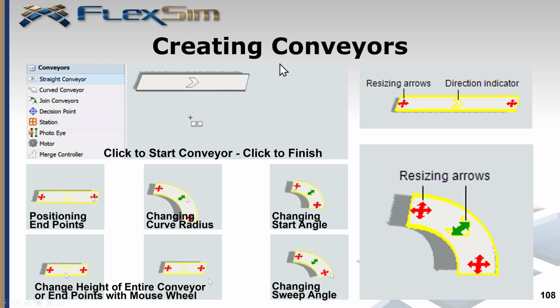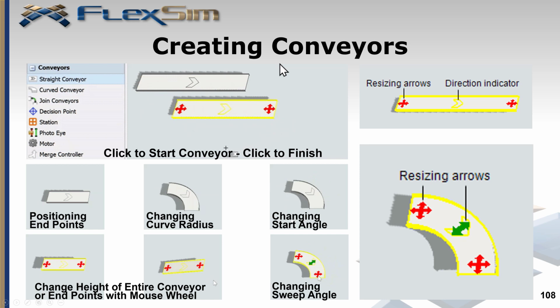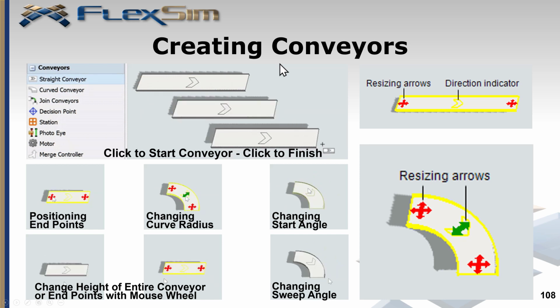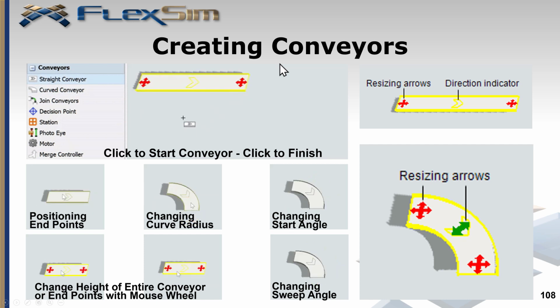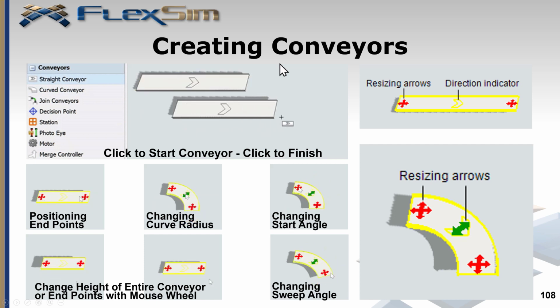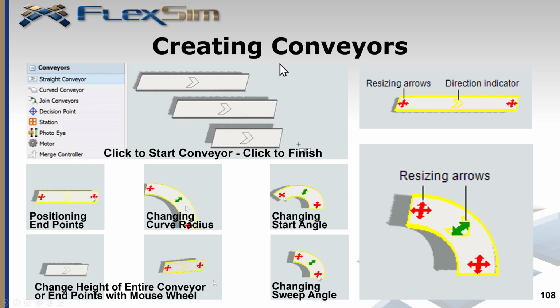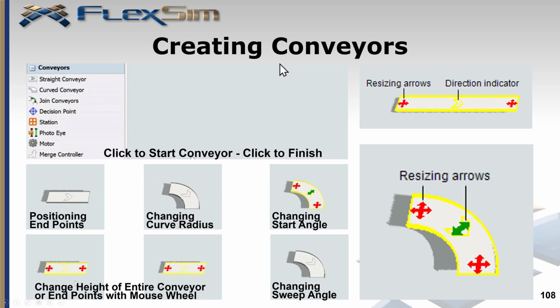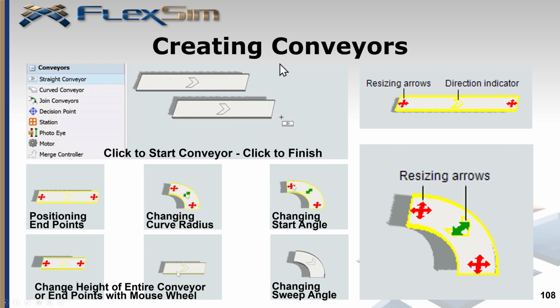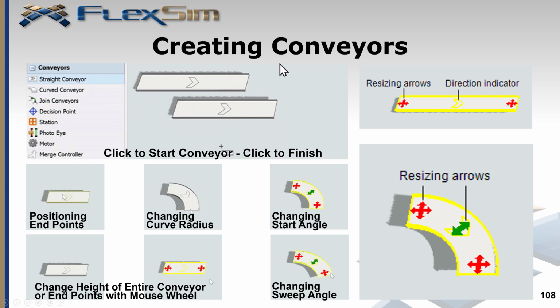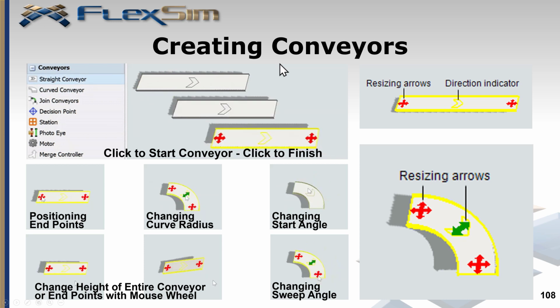However, we also have the option to define the length and/or radius of the conveyors when we first insert them in our models by first selecting the type of conveyor we want in the library with a single click. Then go to the point in the model where we want the start of the conveyor, click, then move the mouse to the end of the conveyor and click again.